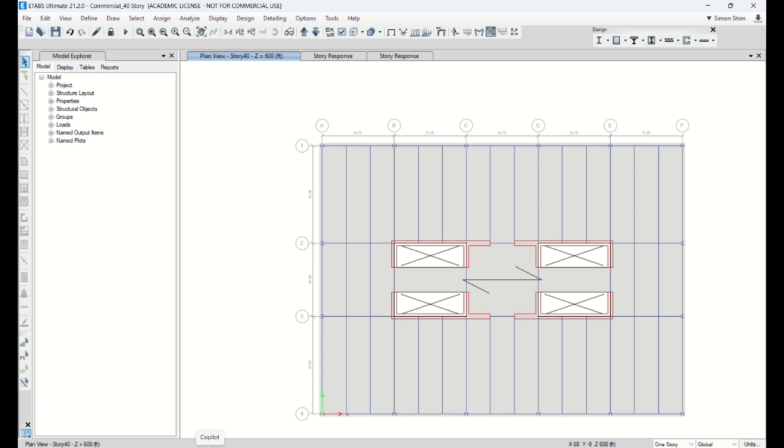By looking at this, you know which direction has more wind effect, right? By looking at the geometry, you should be able to understand which direction has the bigger total wind effect. Obviously, the geometry tells you the wind pressure along the height is the same in X and Y, but your building width is different. So wind blowing in the Y direction is bigger, right?